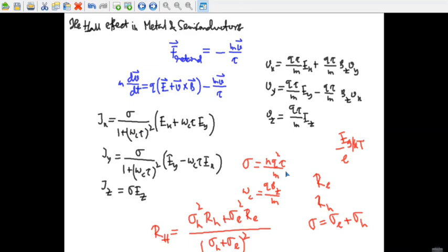Both states carry current, with the hole state acting as a positive charge. The number of these current-carrying states depends on the temperature in a roughly exponential way. The number is proportional to the Boltzmann factor, that is e to the power minus Eg upon kT, where Eg is the energy of the gap, or the band gap energy.